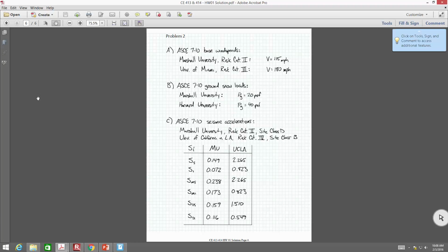One point I will make is we pretty much exceeded that here a couple weeks ago, or at least came close. Keep in mind, when we look up those snow loads, we're looking them up based on recurrence intervals of 50 years. Because of that, when the next edition of the spec comes out, it may not be 20 PSF, it might be 21, because the last couple winters have bumped the averages up a little bit. That's very possible. That's one of the reasons why these specs come out every so often, for things like environmental loading, like snow and wind. The wind stuff doesn't really change a lot. The snow might. And it's just a function of data collection.